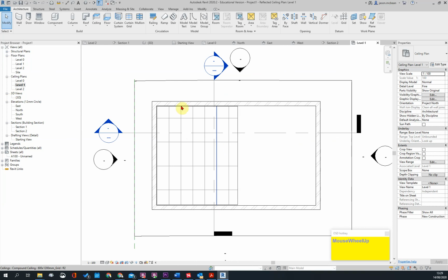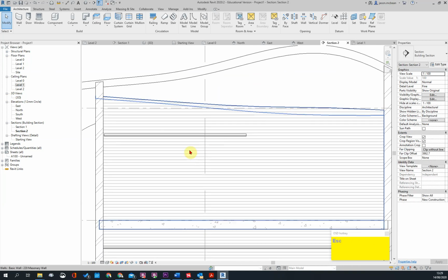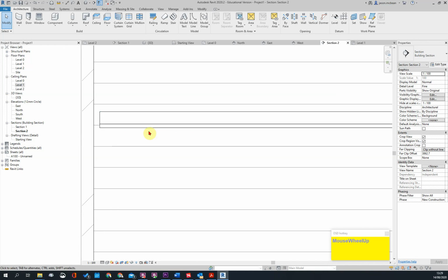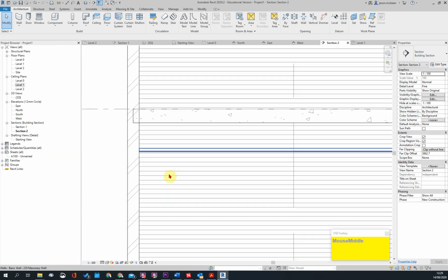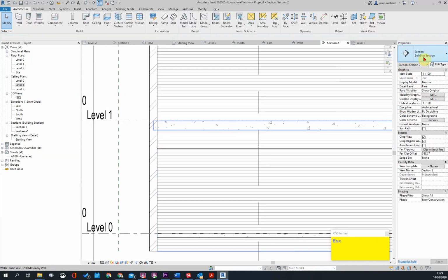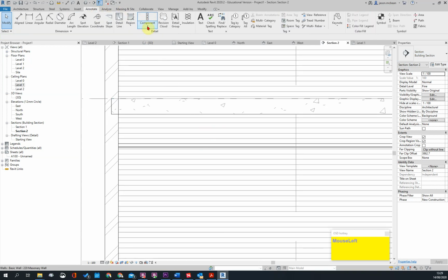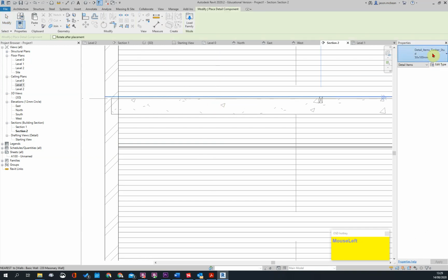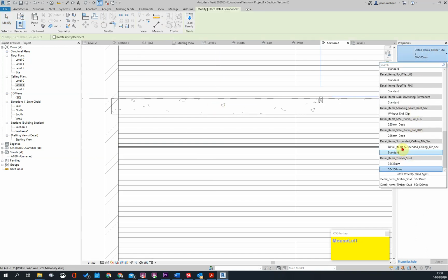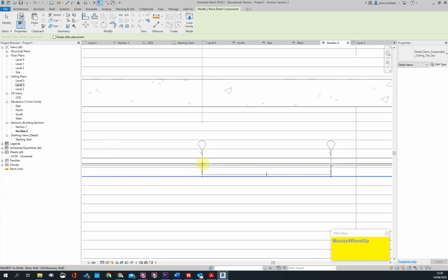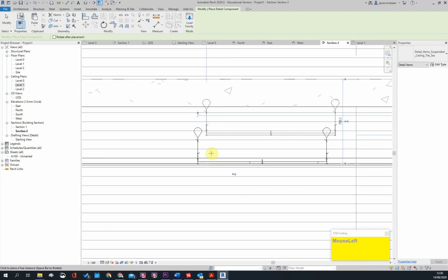Interior architects, please note that you'll be generating ceiling plans and you'll need to start working with ceiling plans as well. And I'll show you these techniques on how to work with these. But in essence, it gives me all the correct materials to work with. So here's my ceiling plan, and what's neat is if you want to put your hanger system in, I go to annotate, component, and there was a detail already here, suspended ceiling, here's my hanger system.